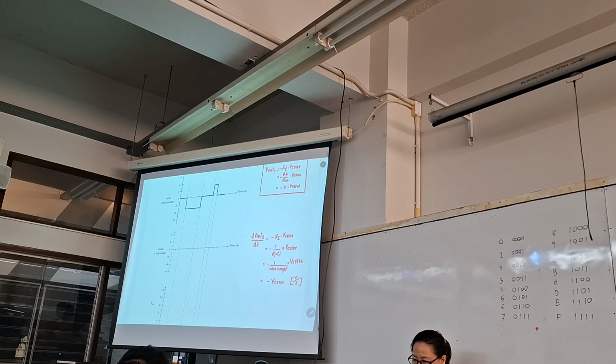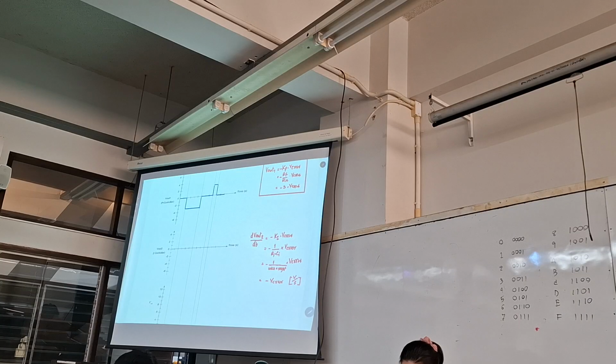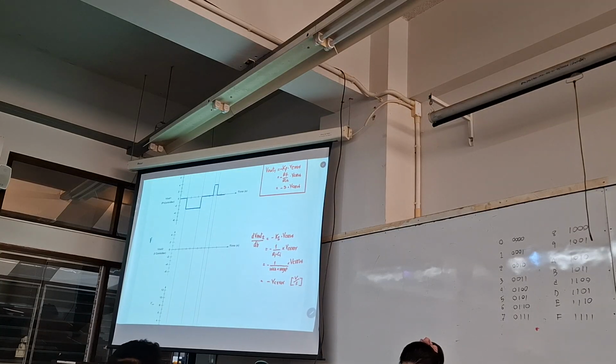Last time I told you that when you make the integrations, you always have a plus V0 at the end of the equations. What is the meaning of V0 at the end of the equations? It means the voltage at the beginning. So I have to define the beginning voltage upon the capacitor that we use in the integrator circuit. And now I will define it as 0 volt.